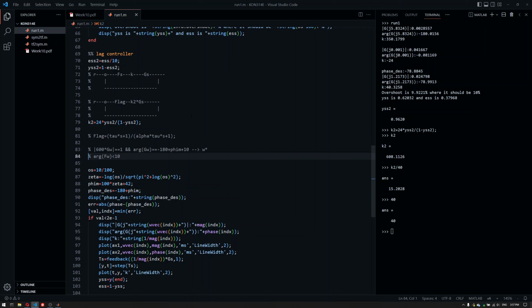If you have a scalar like the P-type controller, it's easy to do some assumptions because it can be positive, negative, it's a scalar. If you have a dynamic controller, stuff in the frequency domain becomes a little bit harder. But for the lag controller, because the lag controller is a special one, you can have some assumptions. For example, the gain should be equal to 1. You can embed the gain into the Bode diagram, so the gain condition is like this.